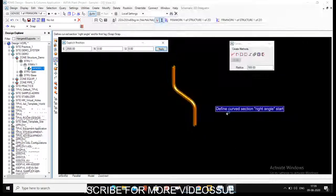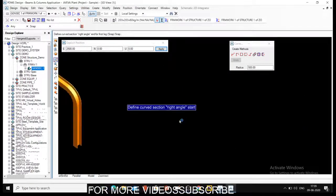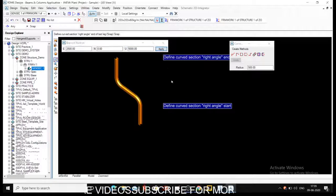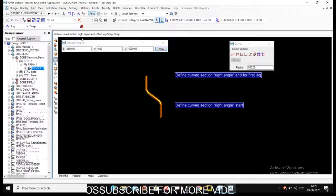So that is the start point for my right angle. Then a prompt will ask for the right angle end of the first leg, so that is the vertical. I want to move it in the up direction by, say, 5000. Apply. And then it prompts for the last end leg, so that is in north, say 2500.